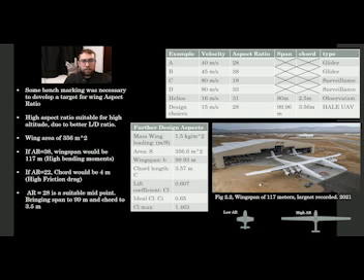So this AR would be unfeasible in a lightweight design, so the span needs to be minimised to reduce bending moments. An aspect ratio of 22, however, would produce a large chord length of 4 meters. This would create excessive friction drag and reduce stability. In mediation of these, an aspect ratio of 28 would span 99 meters and minimise chord length to 3.5 meters, balancing structural feasibility and flight performance within the design requirements.